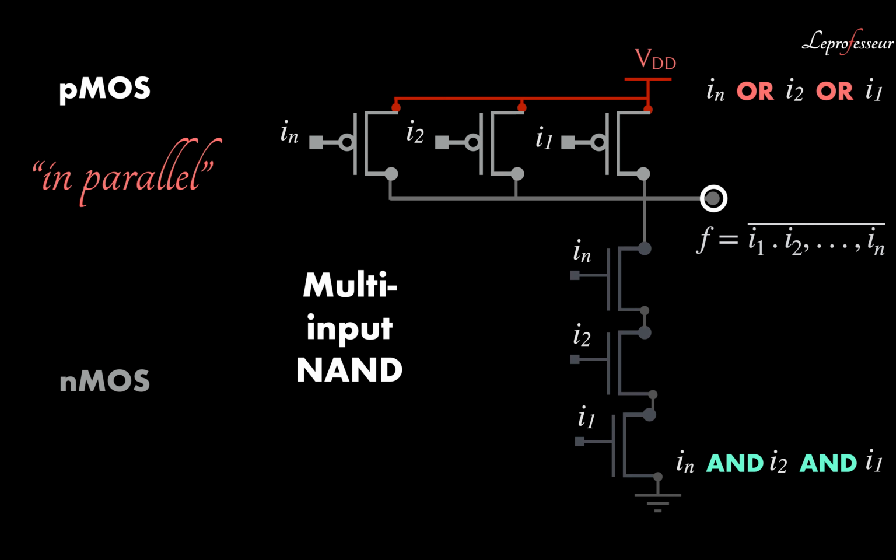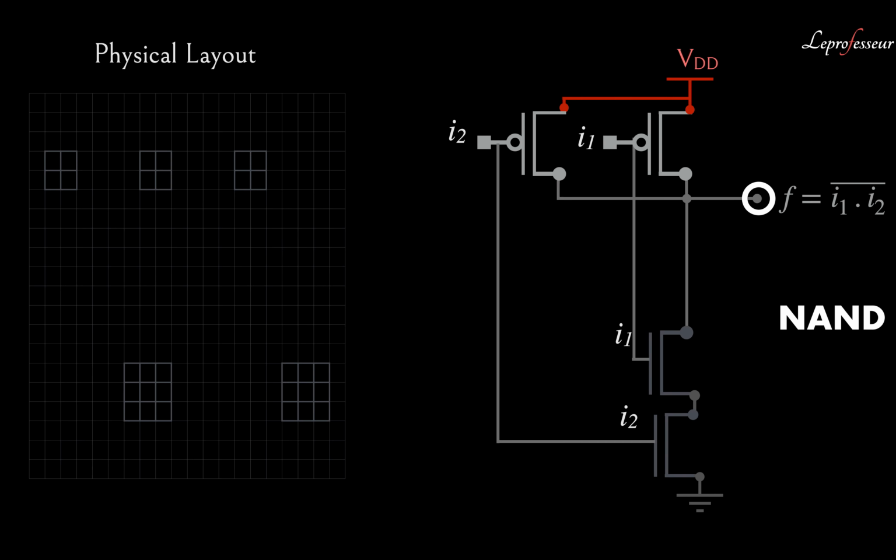So remember, for PMOS, parallel, and NMOS in series. Good. Now let's look at what if we have to draw a layout.